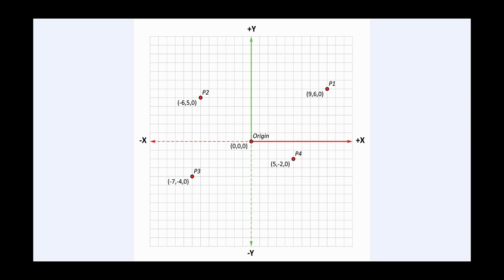Like most 3D modeling software, the Rhino modeling environment uses Cartesian coordinates to locate points and geometry within three-dimensional space. If we look at just the two-dimensional coordinates, we have positive x values and positive y values. Where the x-axis and the y-axis meet is the origin. The values for this are 0, 0, and it's also where the z-axis meets, which is the third 0.